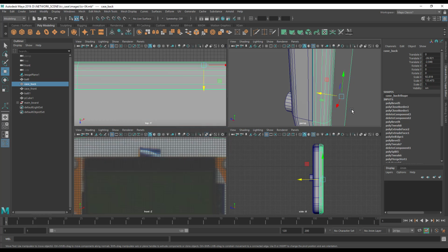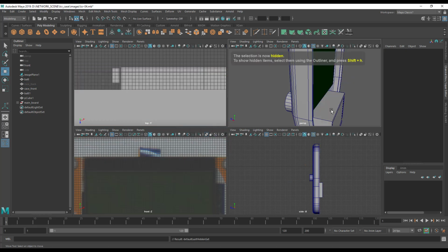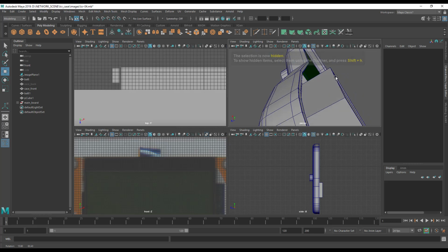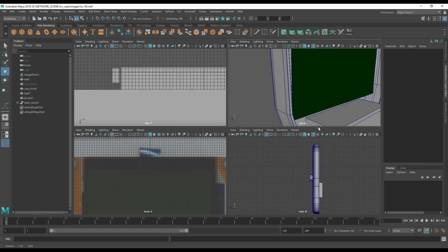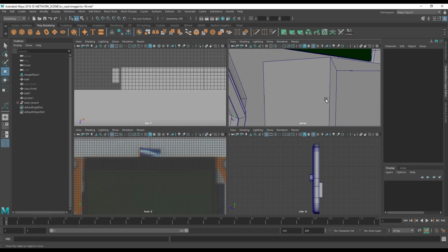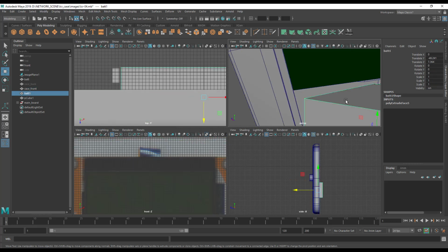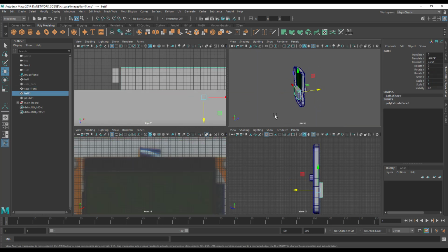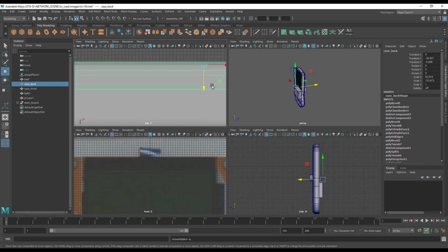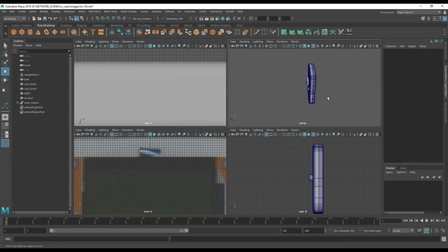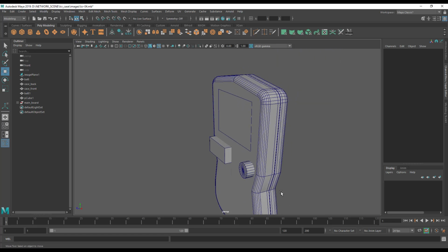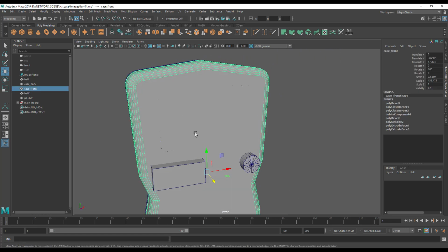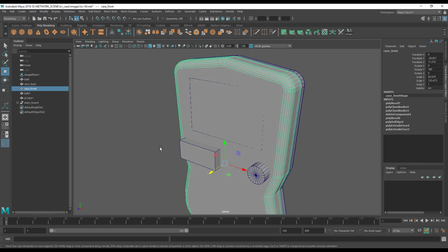Now what we want to make sure, of course, if we hide this one, is that our battery compartment here, or our battery, is not actually hitting the front of the case, and it does not appear to be. That's not much, so we seem to have a good distance. So let's bring the case back, Control H, and there we go. Now that leaves us with a case that's pretty thin. Like I said, I don't really want to print anything that I don't need to. Our screen is just ever so slightly sticking proud, which is not a good thing,